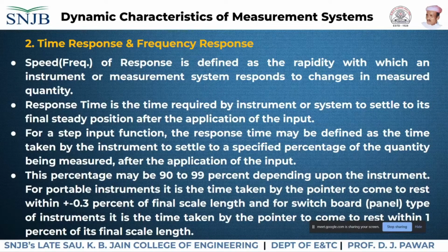For a step input function, the response time may be defined as the time taken by the instrument to settle to a specified percentage of quantity being measured after the application of input. This percentage may be 90 to 99% depending upon the instrument. For portable instruments, it is the time taken by the pointer to come to rest within plus minus 0.3% of final scale length. For switchboard panel type of instrument, it is the time taken by pointer to come to rest